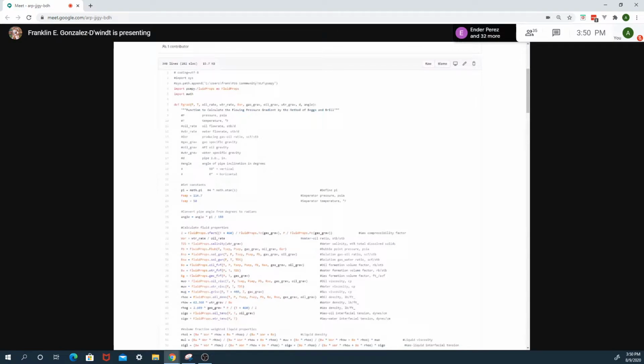The main point of discussion on Beggs and Brill is that when it was developed, all the tests were made using water data instead of oil, and was also made using a very slim pipe of only 1.5 inches of diameter. So there may be some people who don't like it, but this is one of the standards. Hagedorn and Brown is also being used very extensively.